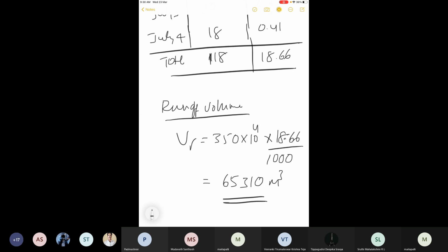The first step is hydrologic design. The second step is hydraulic design. In hydrologic design, you estimate QP, that's the maximum runoff expected from the land area. In the second case, you are going to find out the dimensions of the field drainage or open ditch.